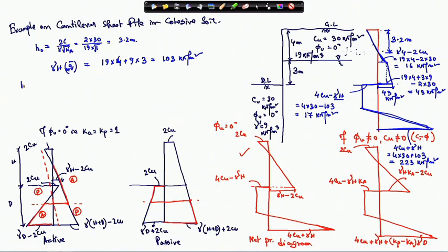First, I will calculate the PA. Okay. So, for PA I am considering only this portion, and this portion is 3.2. So, this height is 0.8, because up to this it is 4 meter and this portion is 3 meter. Okay. So, I am considering this portion as the PA. I am taking this as the PA value, and this PA is at y1 bar from the base of the dredge level, okay, from the dredge level.